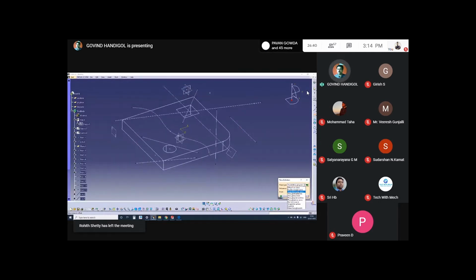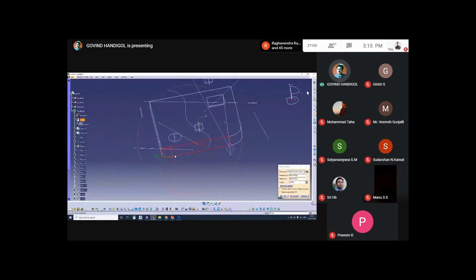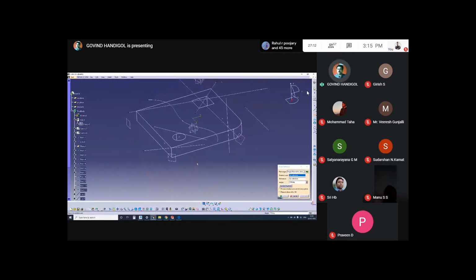Because we need a plane having a working area with infinite length and width always. The size can be increased, but generally it is going to disturb if you increase the size. Then we can go for the angular plane. I would like to keep the angular plane with this as a rotational axis, at 60 degrees. See the preview. Here, we got one plane at 60 degrees. The angle can be customized here, as per your requirement.